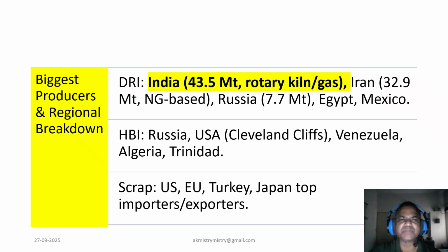As we know, DRI and HBI are high in purity with low residual elements, making them ideal for EAF steel production, and they are basically a premium grade. And scrap, in contrast, has variable quality with higher residuals, which limits its use in certain high-spec steels unless it's deeply processed or blended with DRI or HBI.